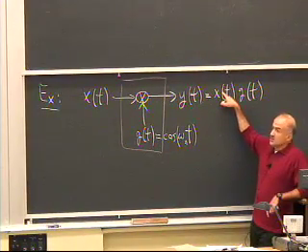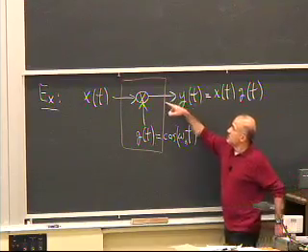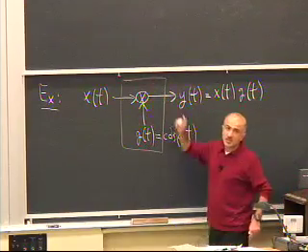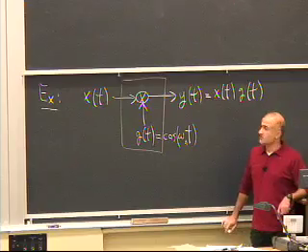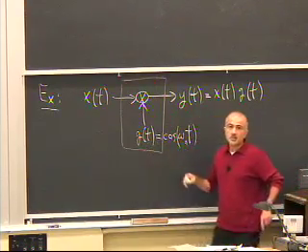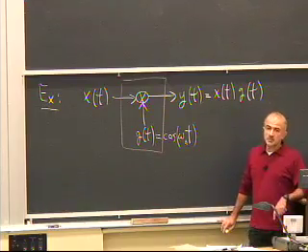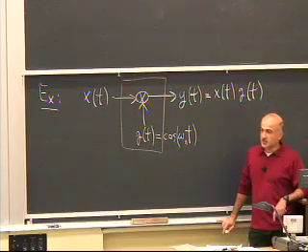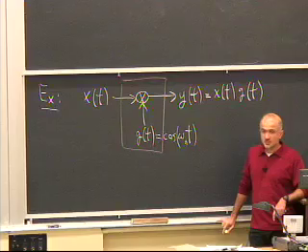The problem is that you cannot implement this system without having memory elements inside. For example, if this is a cosine, that means this system has an internal oscillator. And there's no way you can build an oscillator without inductances and capacitances, both of which are memory elements.